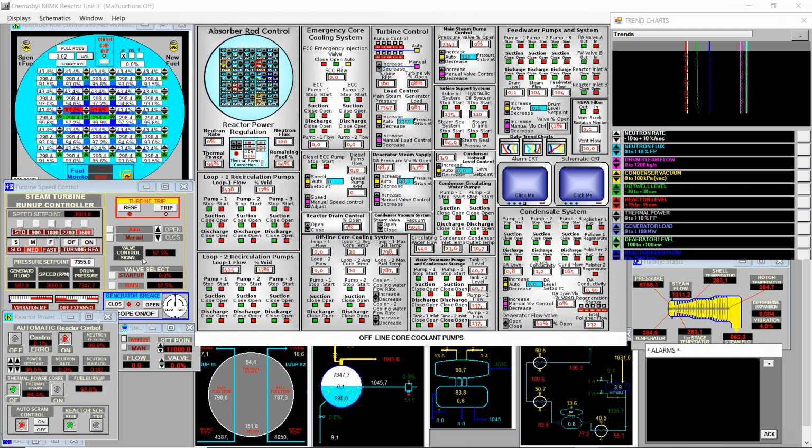I will switch on to manual control in the reactor. So I just look what are the maximum and minimum values, which are 97.9 and 97.5, and set something in between. We see the pressure increasing here, so I can increase a bit to 98, and now it's slightly decreasing. So we are almost at 100% opening of the main valve. Of course we cannot get nominal power until this valve is at 100%, but we cannot open this valve at 100% until we get enough pressure.